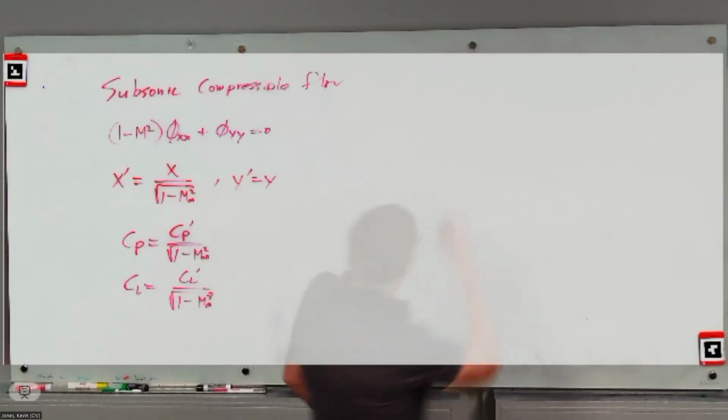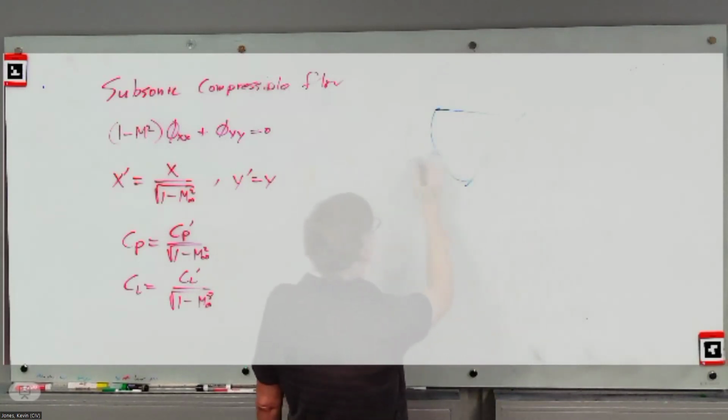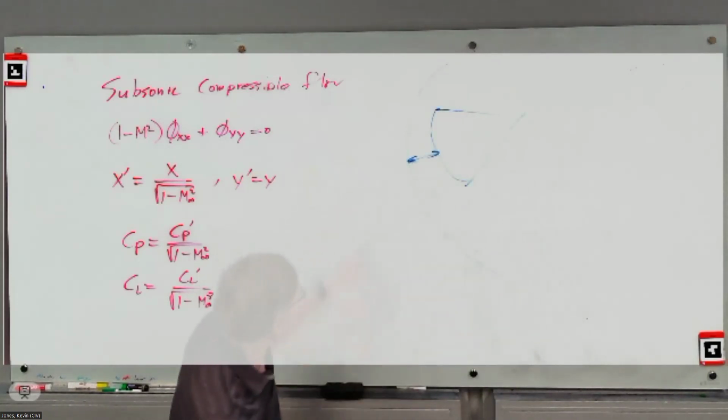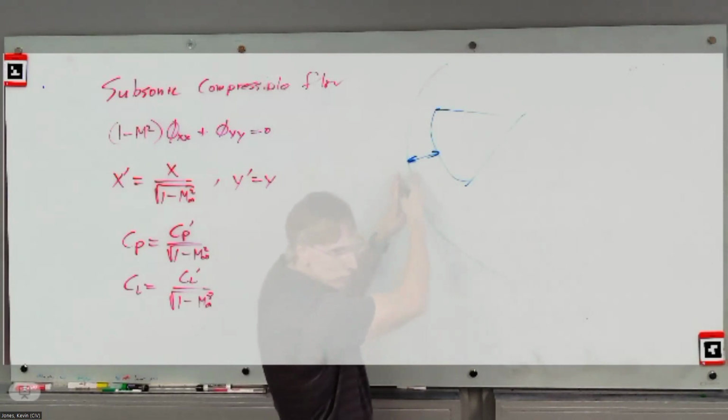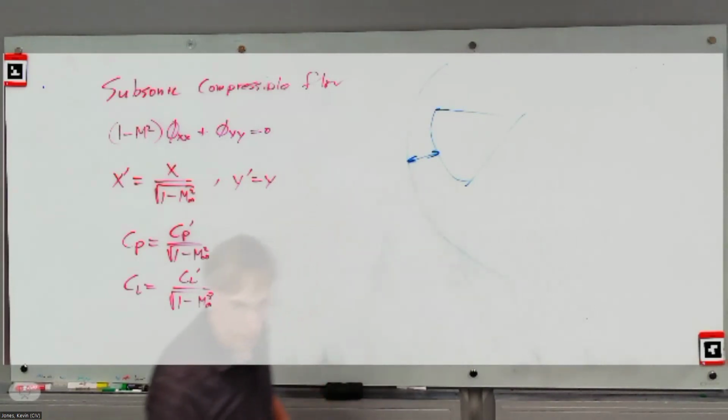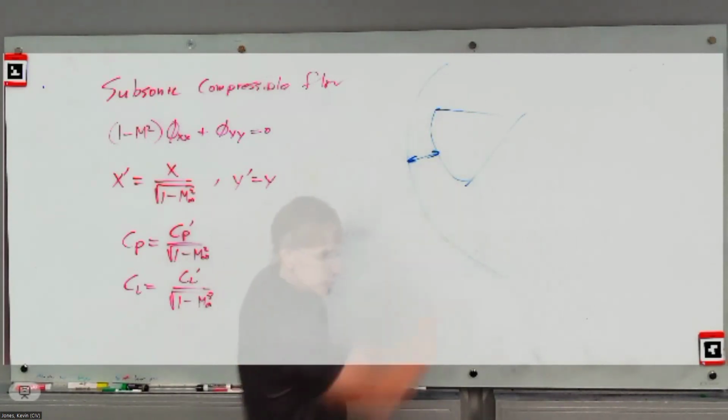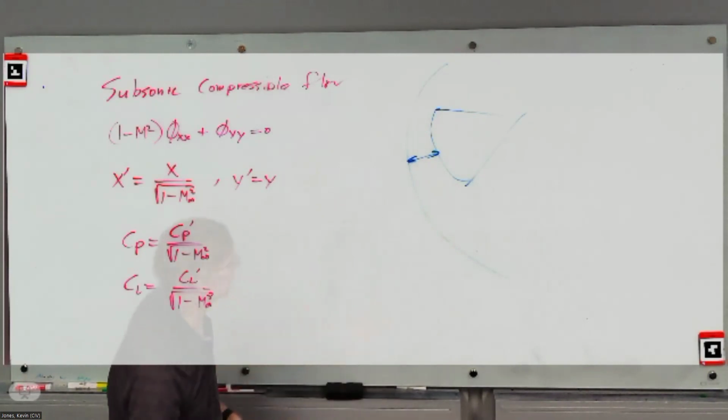And so, classically, we have these capsules, blunt body, it's this huge bow shock. It's fairly significant separation, but it's an incredibly strong shock. Coming in at like Mach 25. So it's ridiculously huge temperature change across here. So we have all that insulation here, plate of materials.